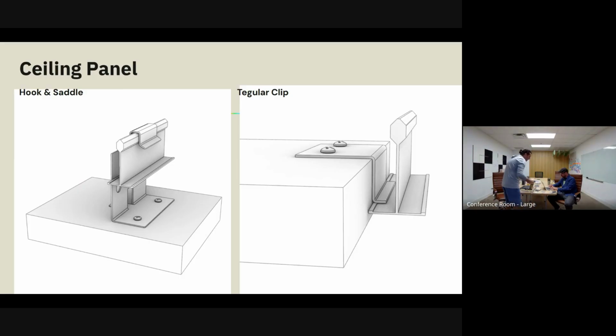I mentioned this, it is important. They have to set their mains on 2-foot centers. One of the things that a lot of people don't realize is when you look at a grid, it's hard to tell which is which, right? But there's mains and what they call crossbars. And the crossbars sit in between the mains and kind of give it that structure of the sizing and all of that.